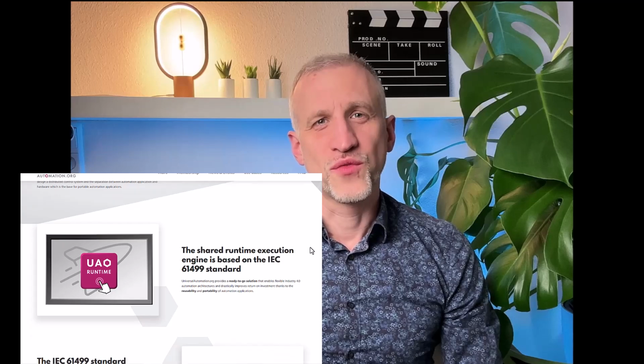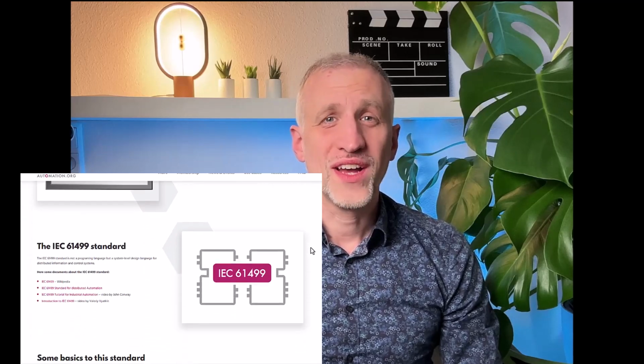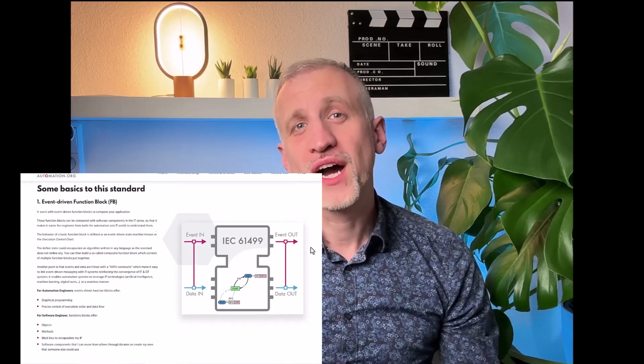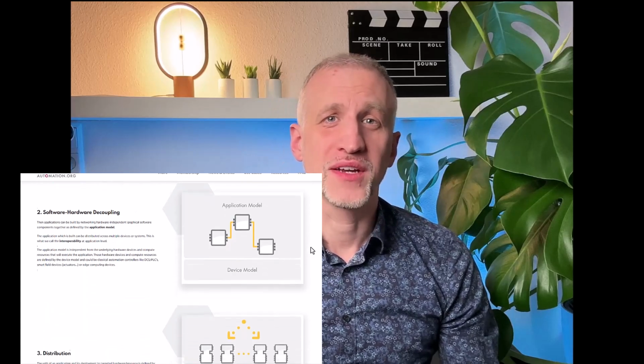Unlike the old PLC standard 61131, which still runs cyclically, where variables are scattered in different sections and one programmer can barely understand another one's code, IEC 61499 uses an event-driven approach combined with object-oriented programming. If you like programming languages like C++, C#, Java, JavaScript, or Python, you will feel right at home.